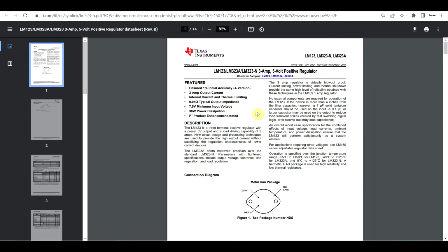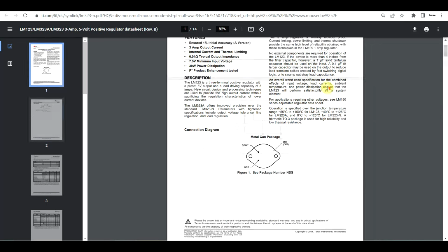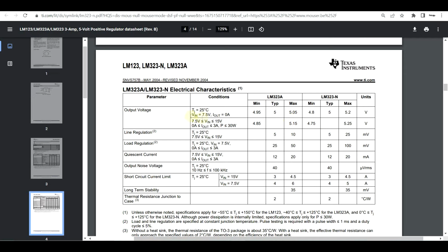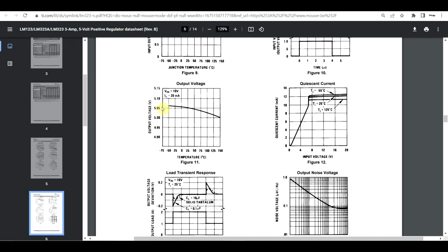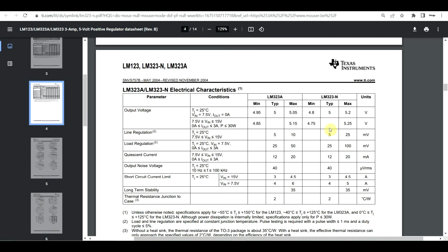Now, most power supply datasheets, like this one for the LM323, will give an indication of the output voltage range under some specific test conditions, which keep the circuit in its normal operating range. So you will have an initial tolerance in the internal circuitry, and then by varying the various parameters, the total output voltage will end up having a slightly larger variation. So things like supply voltage, output current, and even temperature will have an impact on the exact output voltage that you're getting. Now, depending on the exact circuit that you are using, you can have better or worse tolerances.